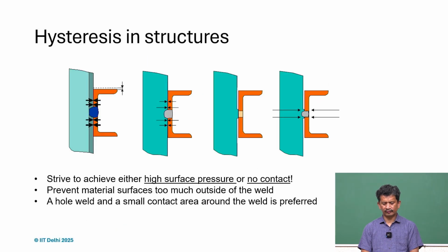So there are a lot of design rules or guidelines, wherever we have this kind of clamping and want to put things together, whether the load is in tension, compression, or rotation with torques applied, on how to take care of that. As we said, hysteresis in mechanisms or in structures and frames is detrimental for precision. So that's why it's very important to understand.